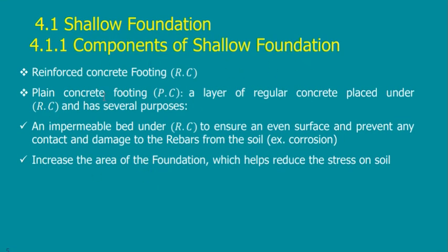Components of shallow foundation. We said it as we were going, but we will just list them now. I have something called the RC, which is the reinforced concrete part. This is the main part of the foundation. It's similar to the PC or the plain concrete, but in addition it has rebars or reinforcement, and of course the quality of the concrete is higher. If you are using two different grades of concrete, then you put the better grade for the RC, and you put the lower grade for the PC.